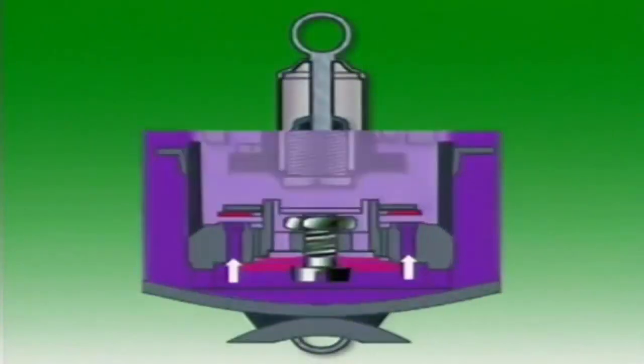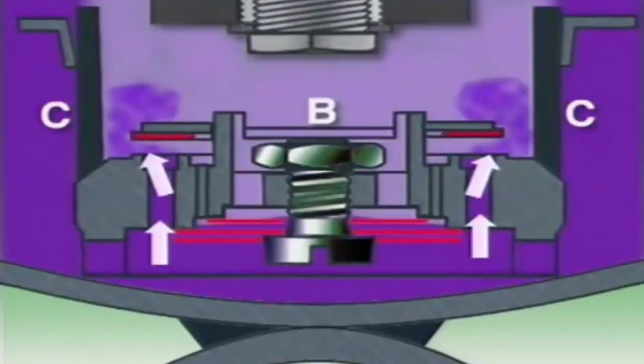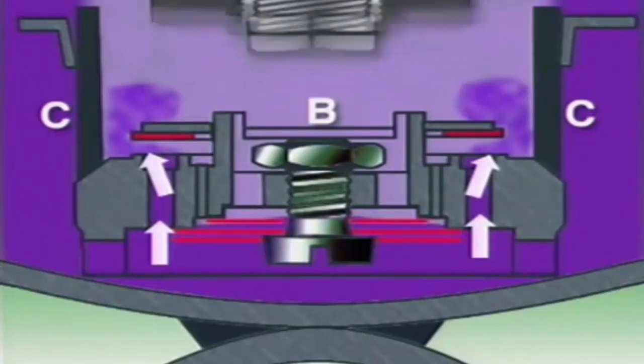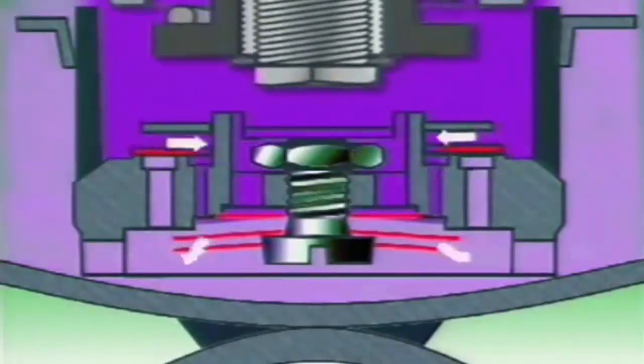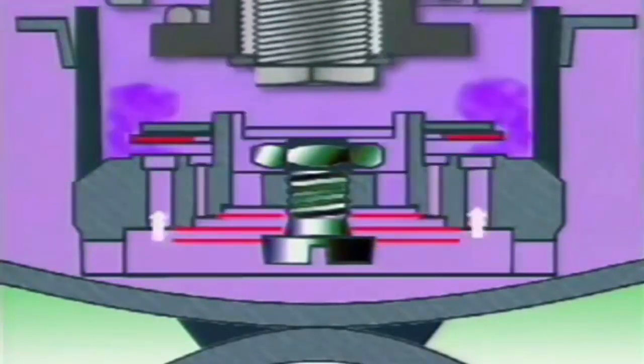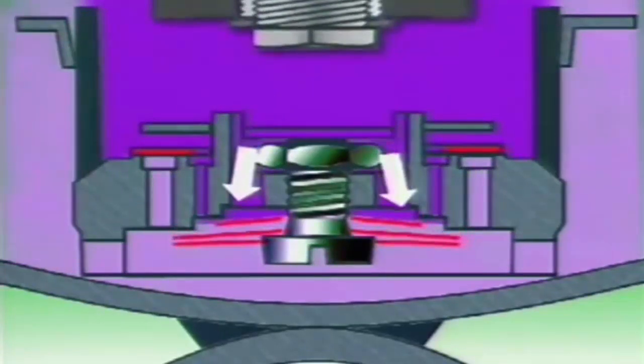Pressure in B falls below that of the reservoir, causing the base intake valve to be unseated. Fluid flows from the reservoir into chamber B, keeping the inner tube full. The valves provide control over the amount of force required to pass fluid through them at any given piston velocity. They can be made to open in stages according to fluid pressure.